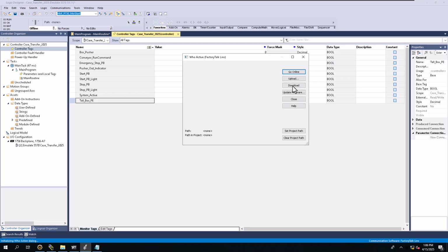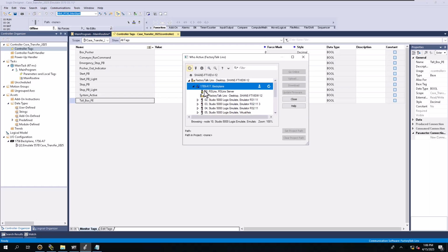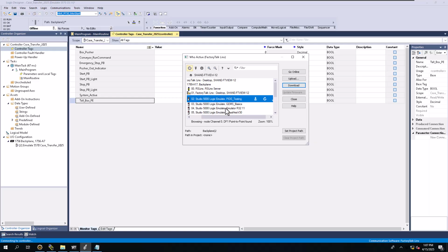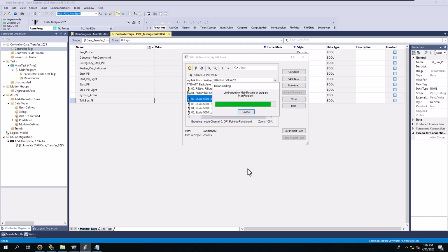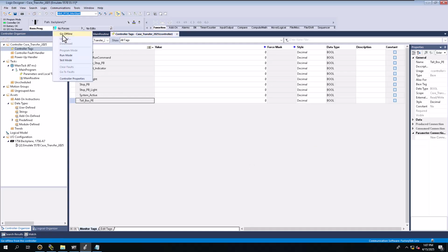So we're going to go ahead and download that PLC program to the processor that we had, the ABB BBP1. We're going to download that, even though we didn't do anything yet. It still made the OPC connection, still made everything valid. Now we may have to stop that connection and restart it. I don't know. But when it comes down to it, the PLC was not downloaded to the processor at that point in time, so the tags that are currently there may get updated automatically. It probably depends on the version you're running.